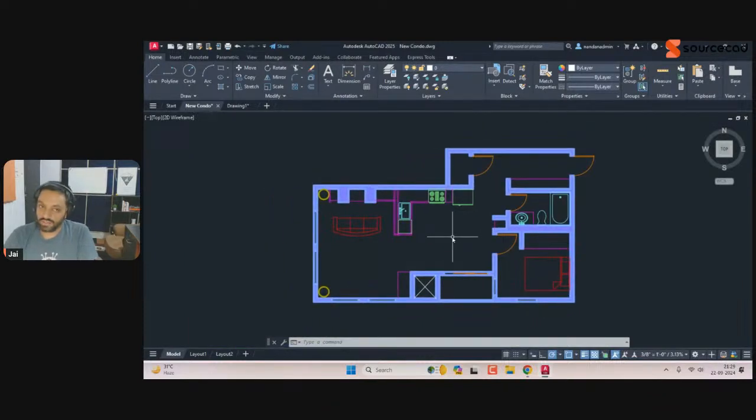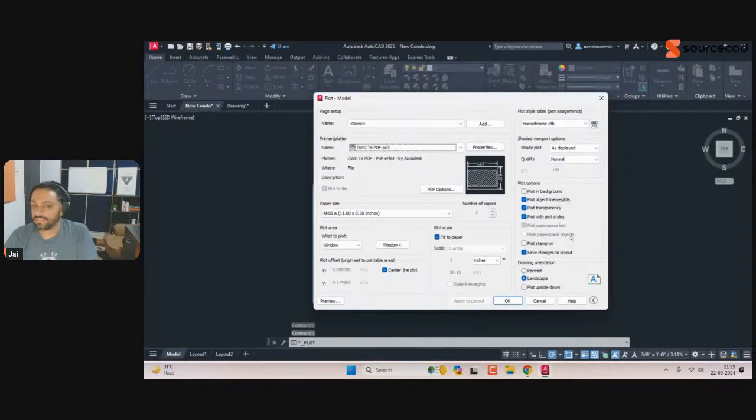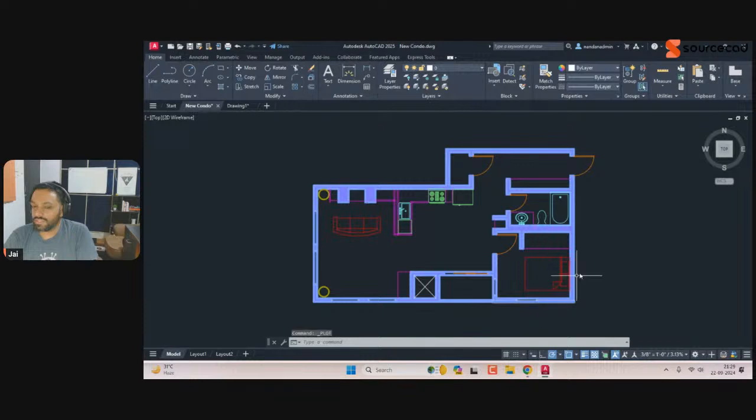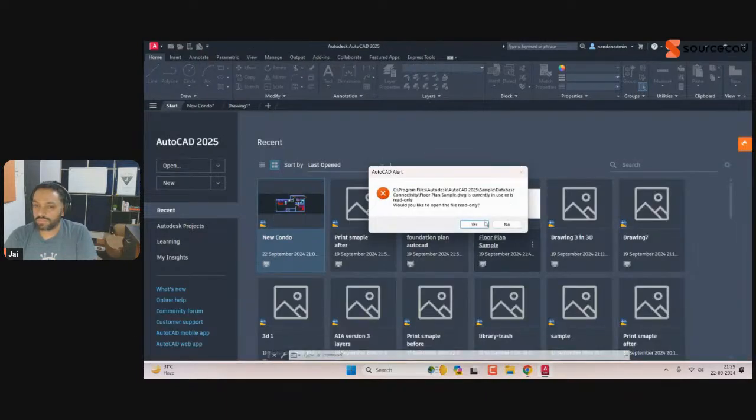But here's the thing. Every time you go to this print option, the settings here, they just reset. In my case, they are not resetting. So why is this happening? I mean, is there something special that I've done? Because every time I'm just going to this print option, it's just starting from my last settings. It's just not resetting it. Well, the reason is I have created a page setup, and you should also do that if you use the same settings every time. Because if you don't do a page setup, let me show you an example.